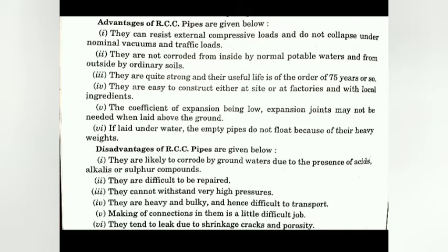Next, when we come to the fifth point, the coefficient of expansion being low, expansion joints may not be needed when laid above the ground. So when we compare with the steel pipes, when they are subjected to heat, there is a chance of expansion of the material. But in this case, the coefficient of expansion is very low. Only in case of the RCC pipes we have some sort of expansion. Otherwise, the factor is very low. Because of that, we don't need to provide the expansion joints